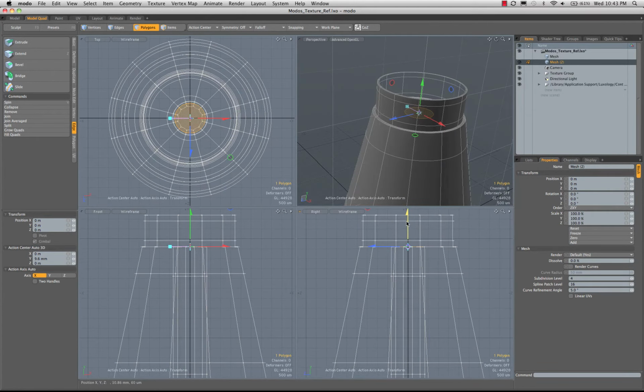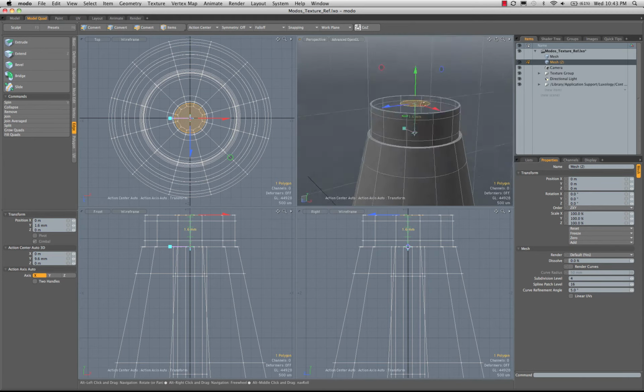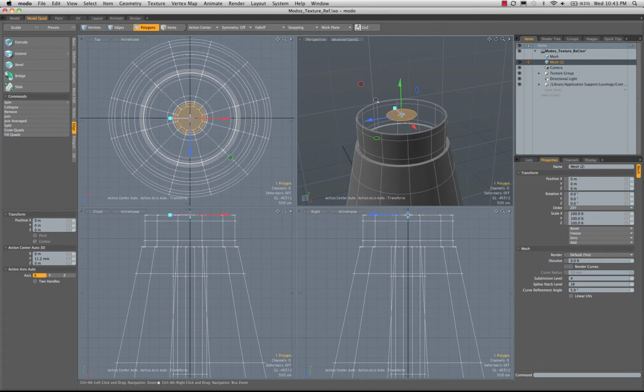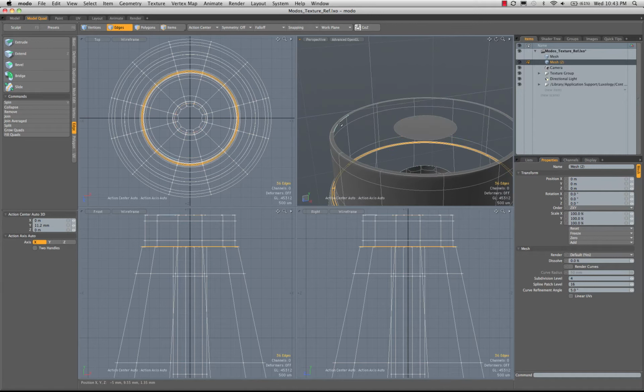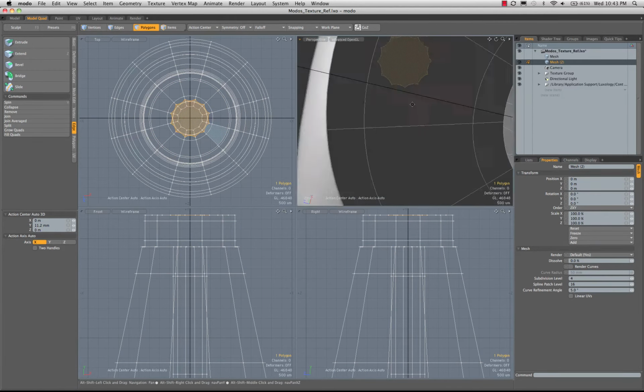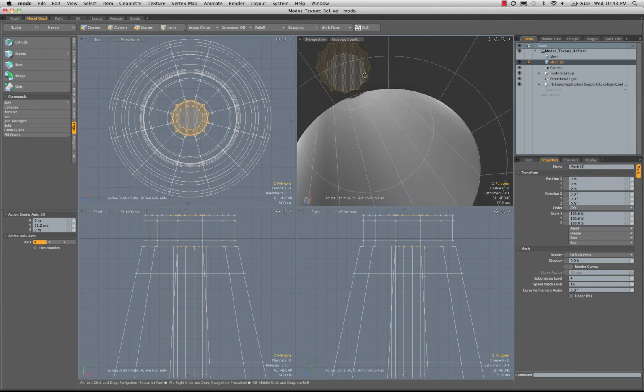Should be 1.5 millimeters if I'm not wrong, or 1.6, one of the two. Yep, 1.6 looks like. So we get that up into the right place, and then I'm going to flip that one, unhide the other one, which I didn't have to do right at this moment, but not a bad practice. And so I'm going to select these two edges, bridge. Now I'm going to select this polygon and this polygon.